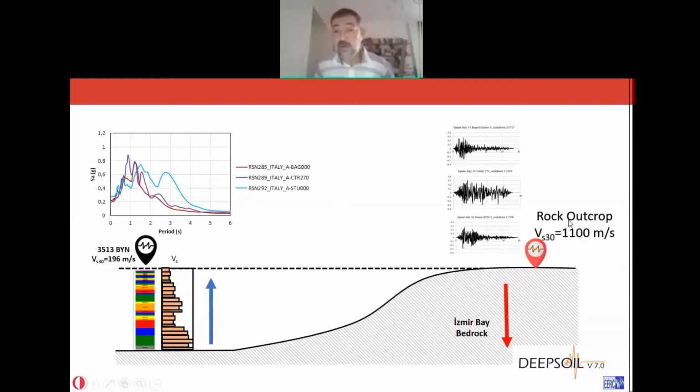Again, a deterministic scenario. Please understand the uncertainties. And also, we believe this is unconservatively biased. Remember, ground motion equations are a little bit exceeded at the rock site, so these will probably be exceeded by a real event. As compared with the design basis elastic response spectra, I'm not saying buildings will collapse or be damaged. Remember, this is an elastic response spectrum.